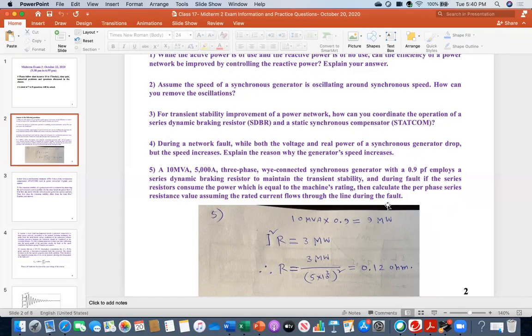So therefore, those who used the voltage cannot use the voltage, because this is a series connection. Voltage is between 2 points, so there should be an element between those points. But it is not line to neutral; it is a series connected thing. So you must go through the current I. That is the significance of current and voltage: current is for series, voltage is for the parallel case. That's why there are two equations, I square R and V square over R. Okay, so that is fine.